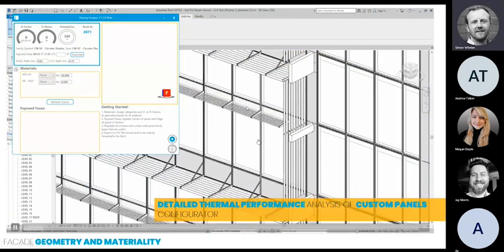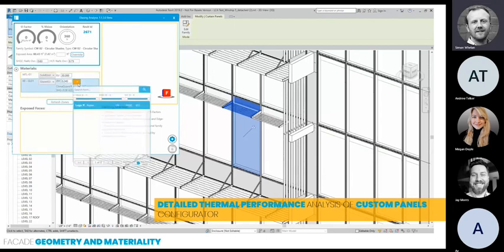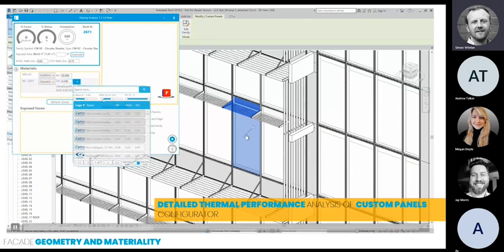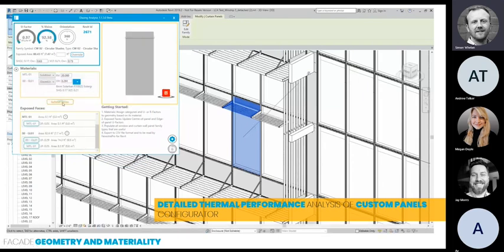I think this is just a repeat of what we saw a few minutes ago, but needless to say, the more detailed stages you're really getting into, or maybe as a facade engineer, maybe you never touched this, getting into some of the weeds around your facade. So for example, glazing will have a center pane U value, but it will also have edge of panel values in accordance with NFRC, and that U value may not be the same, will not be the same.